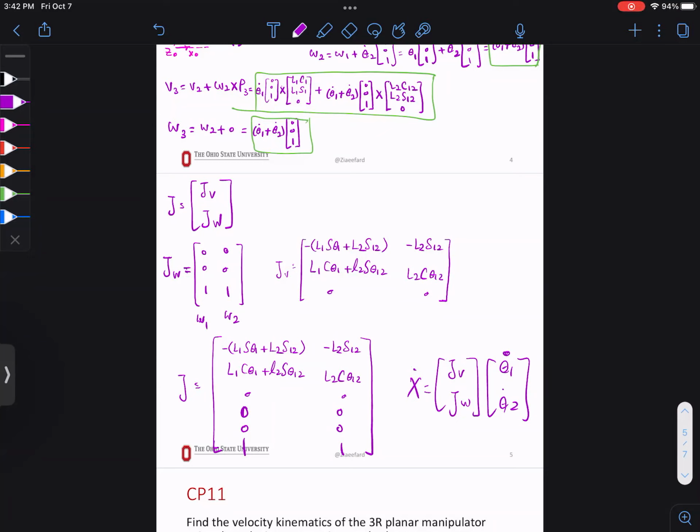So you can use something called a reduced Jacobian. Every one of these parts, you can separately find that one and this one, and find the determinant and multiply. Or you could use the reduced one, but you need to know that this is what you did. All right, so when you find the solution, you have to look at the robot. Does it still make sense? Now, for the robot we had in last class, theta 2 equals 0 was one of the singularities, right?